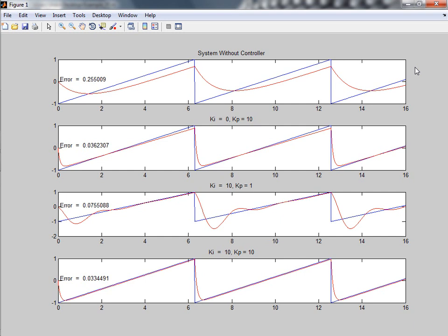Is the uncontrolled system the open loop system, or is the uncontrolled system closed loop? There is a slightly different definition between the open loop control system and the uncontrolled system. If you say the open loop control system, still you have the proportional gain for any kind of the control, but there is no feedback. When I say uncontrolled, there is just a plant. This is a controller. Yeah. Uncontrolled system is no control.